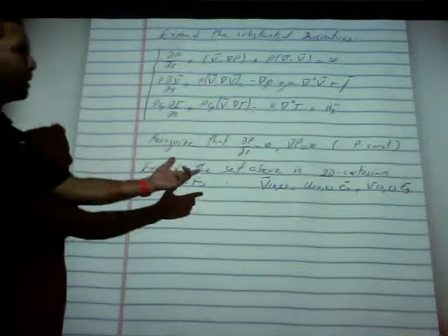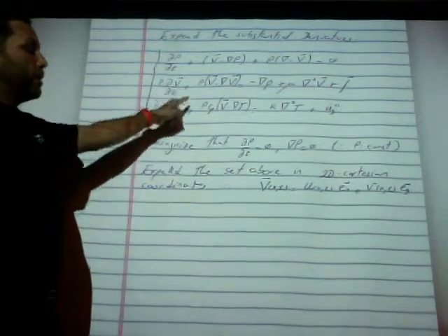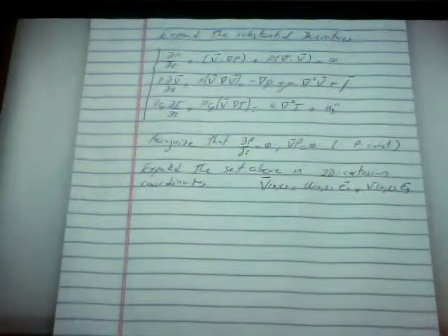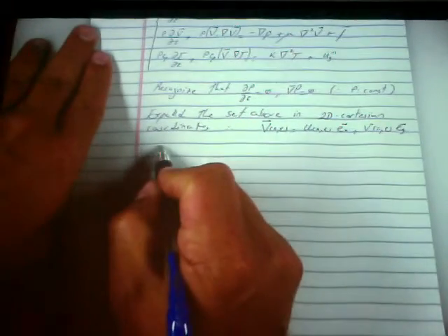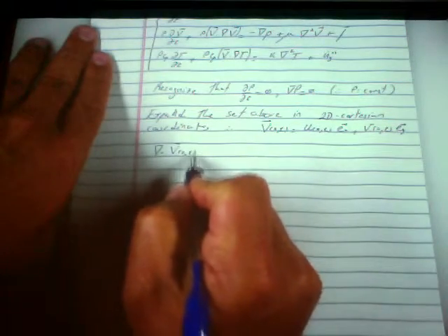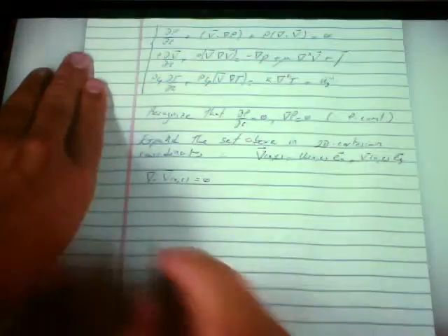Okay? And again, recognize that the velocity field is a vector field that has an x component and a y component. They are completely independent of each other. So, this set of equations will turn out to be the divergence of v of x and t is equal to 0. That's the first equation, because the density goes away.